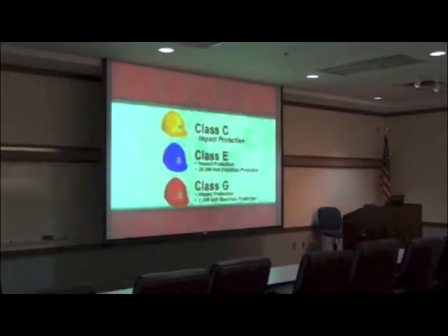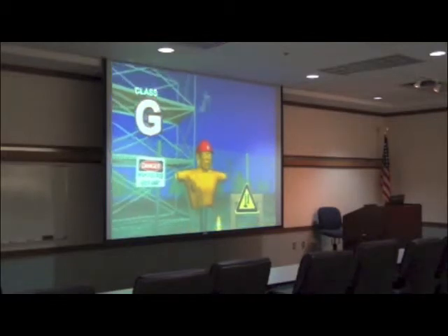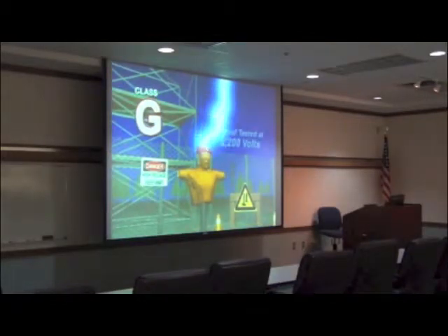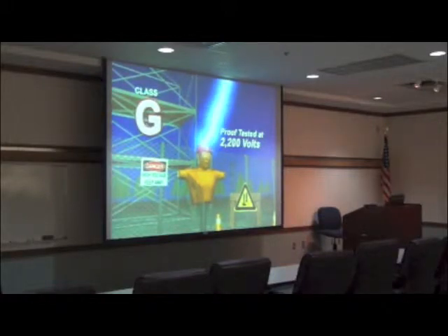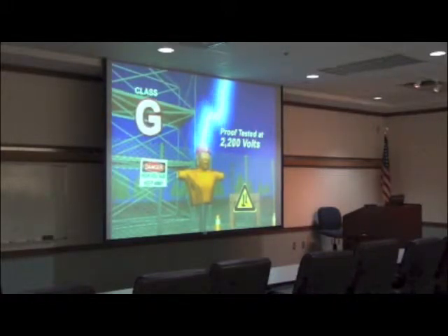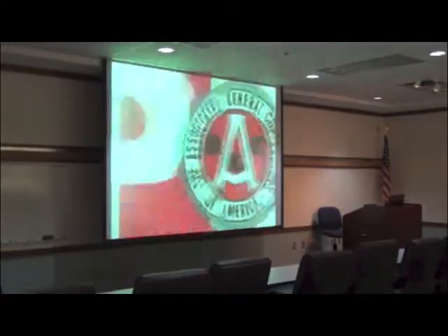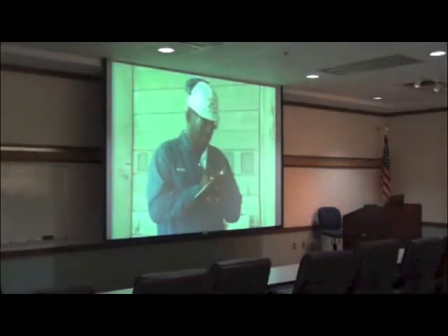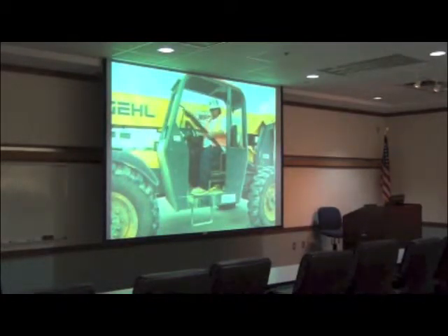Class G helmets are intended to reduce the force of impact of falling objects and to reduce the danger of contact with exposed low voltage electrical conductors. For certification, sample shells are proof tested at 2200 volts of electrical charge. Whatever hard hat you wear, make sure it fits properly. Head protection that is either too large or too small is inappropriate for use.